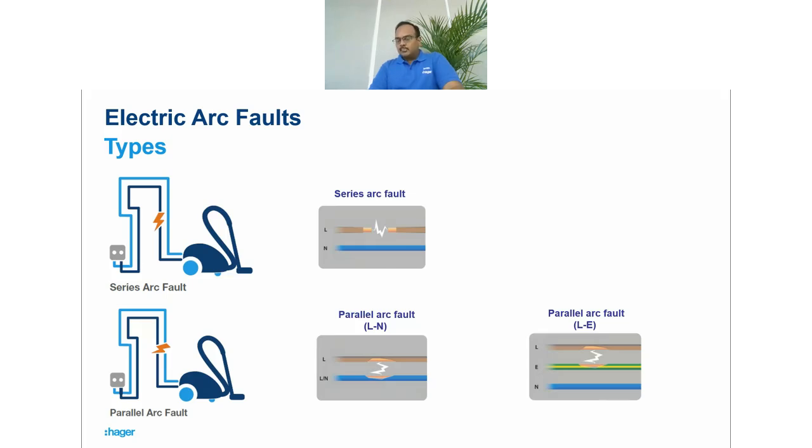But our MCB is 10 amps. But here this will happen in a different curve that the MCBs cannot detect. So this is what has happened. Neither our MCB nor our RCCB can detect these kinds of arc faults which are happening today. And its waveform and its magnitude are completely different from the curves we have for MCBs. So this is an important understanding we should have.